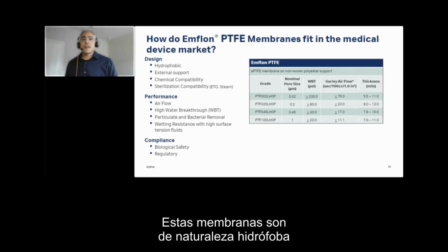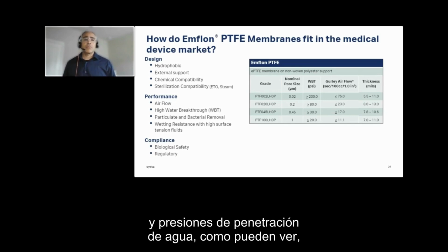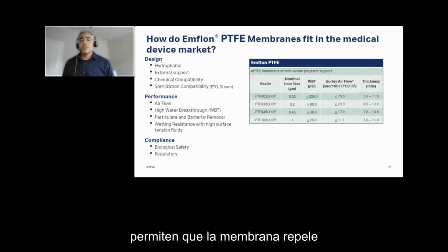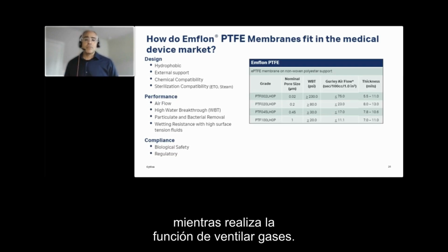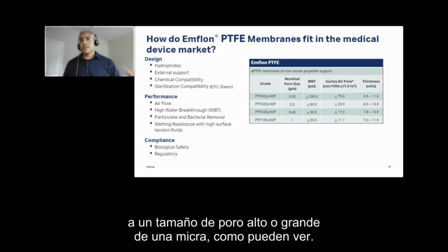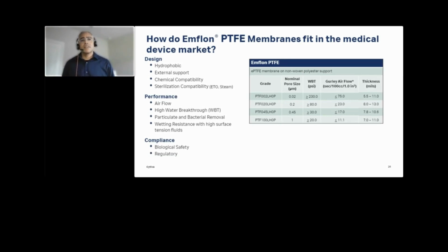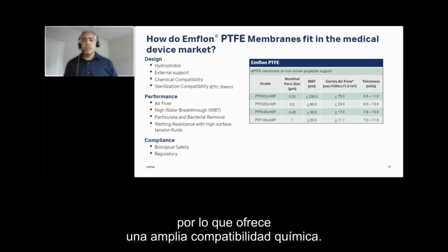These membranes are hydrophobic in nature, and their high water intrusion and water breakthrough pressures, as you can see, allow the membrane to repel high surface tension liquids at high pressures while doing the function of venting gases. In this product family, the pore size offering is limited to a high or large pore size of 1 micron, as you can see. And one other point is that PTFE is an inert material, so that does offer broad chemical compatibility.